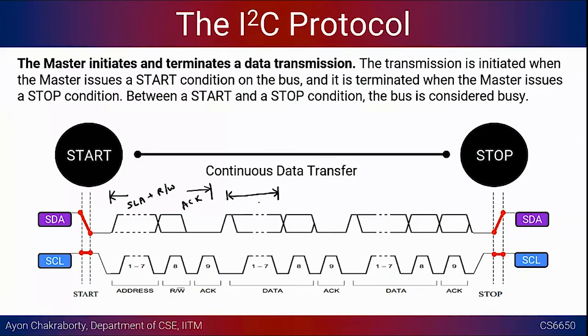For writing data, you need to tell it where you want to write data, because it will also have a tiny fragment of memory, right? Where data will be stored or some kind of configuration settings will be stored. So it is often the practice that you also send some kind of register address, or I would say some kind of control information. Once that control information goes to the sensor, it knows what exactly to do.